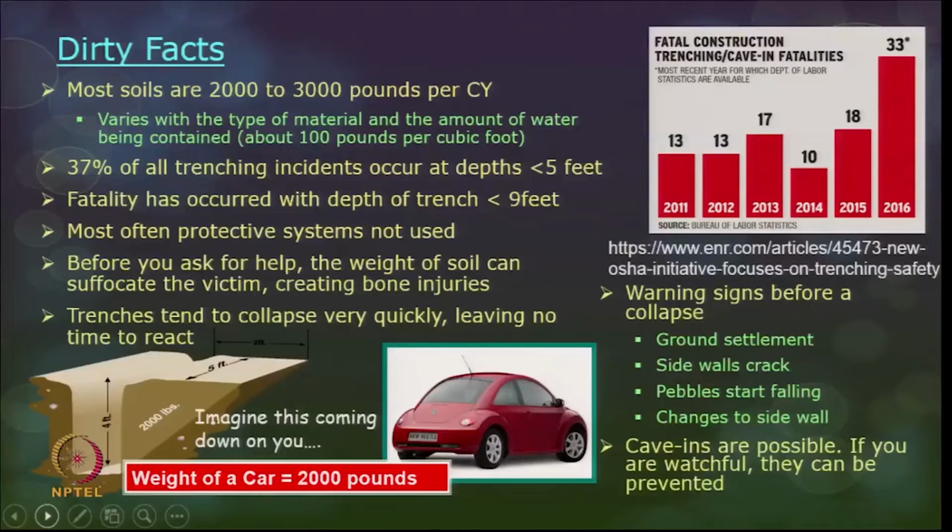If you see the statistics on death or fatality with regard to trenching or cave-in incidents, 37% of these incidents have occurred at trench depths less than 5 feet. So, it is not too deep, but still many fatalities have happened. Ironically, the deeper you go, there are fewer fatalities, as adequate safety precautions are already in place.